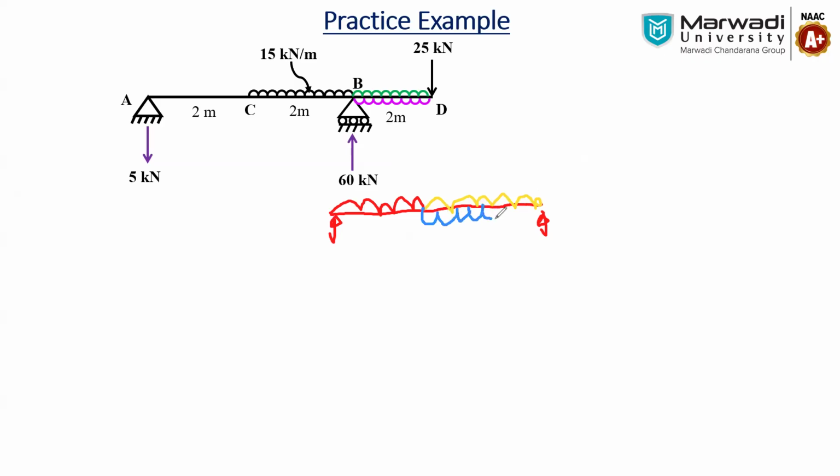So whenever we write the equation of the Mx, we have to consider both the UDLs, right? Because the upper UDL we are anyway going to continue in our section, but we have to consider the opposite UDL also, right? So let's write the equation of the Mx over here. In the first section, we will cut in between the A to C. So it is something like this.